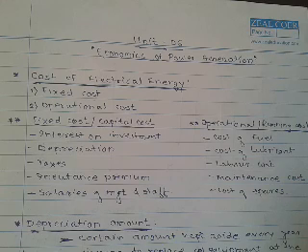So calculation of monthly electricity bill is based on the energy consumed by that particular customer. It is calculated by using a simple formula, that is consumption of energy in a particular month is equal to the product of the quantity of appliances, its capacity in wattage, the number of working hours, and 30 days, that is the days of a month. By using this simple formula we get the monthly consumption of a particular customer. By using this we can calculate the electricity bill easily. You can better understand how to calculate the monthly electricity bill while solving the numerical.